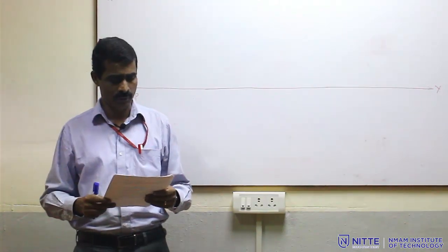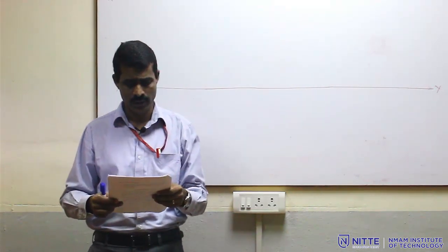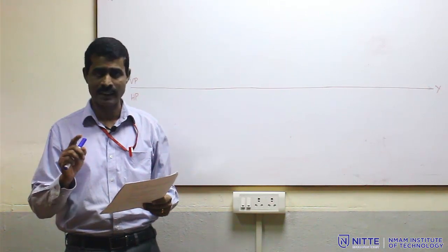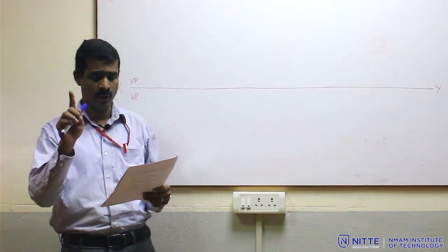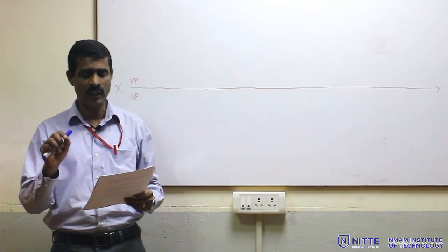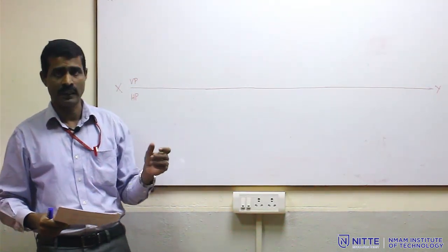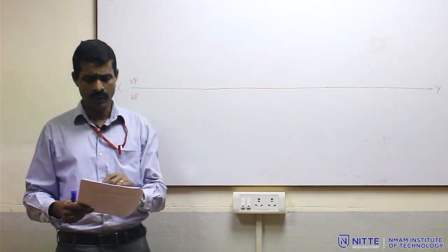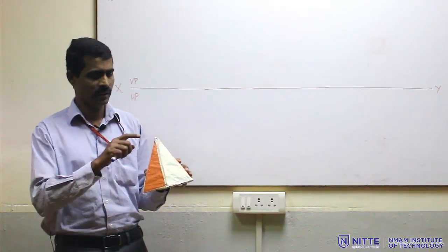Let us solve another problem on a hexagonal pyramid, that is problem number 4 from the question bank. I will read out the problem. A hexagonal pyramid, 25 mm sides and axis 40, as I mentioned, always side and axis height will be given. Rest on SP on its base such that one of the triangular faces is perpendicular to SP. I am coming to the second criterion of conditions given with respect to SP: the triangular face perpendicular to SP and parallel to VP and nearer to VP.